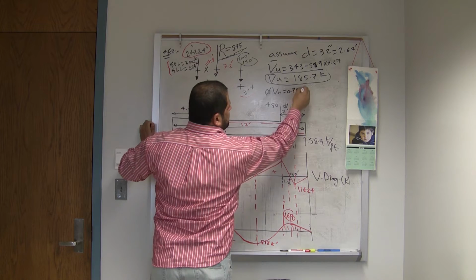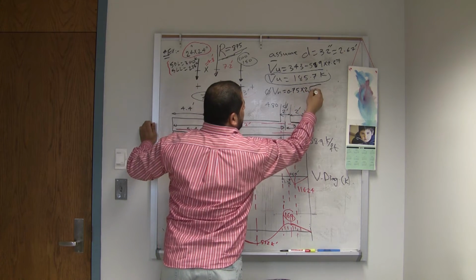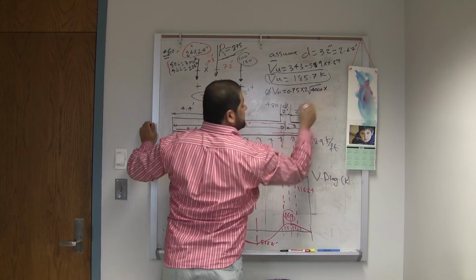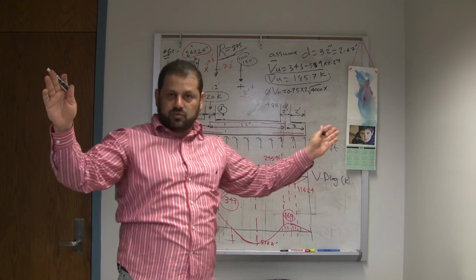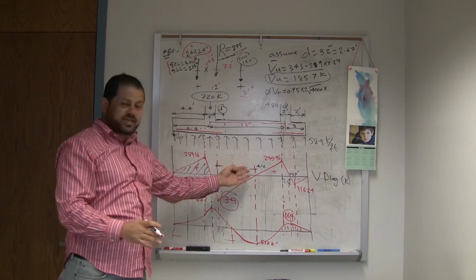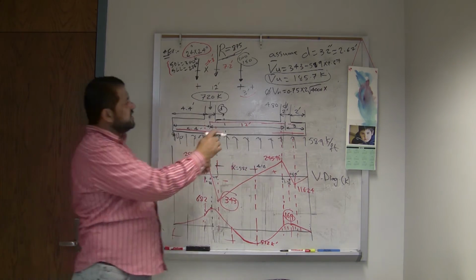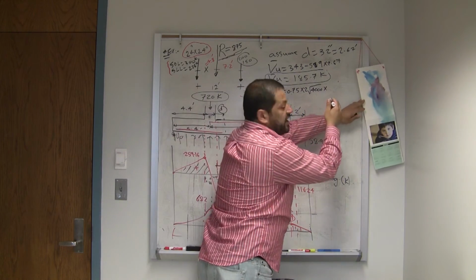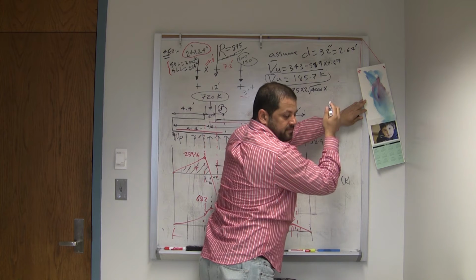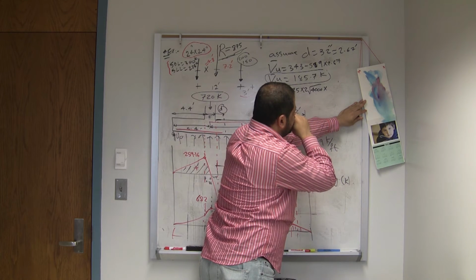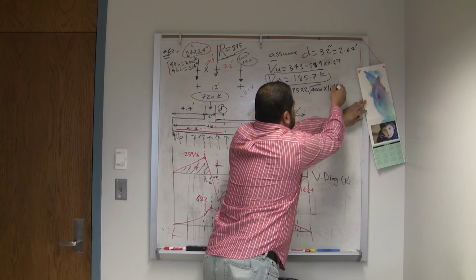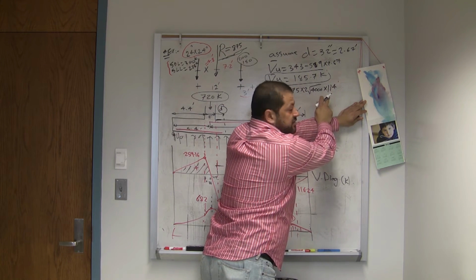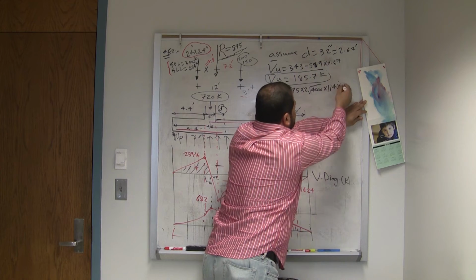So phi VN equals 0.75 times 2 square root of 4,000 times B. What's B now? B is 9.5 times 12, the width of the footing, since everything is calculated for the full load. 9.5 foot times 12 is 114, times D, the assumed 32.